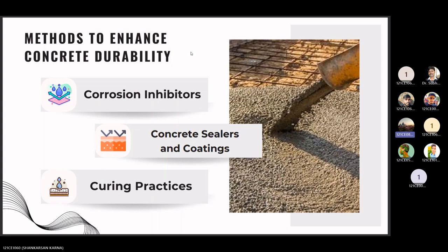Next is concrete sealers and coatings. Applying sealers or coatings to concrete surfaces to provide a protective barrier against moisture, chemicals, and abrasion. Sealers can also help to reduce water absorption, inhibit chloride entry, and enhance surface durability.